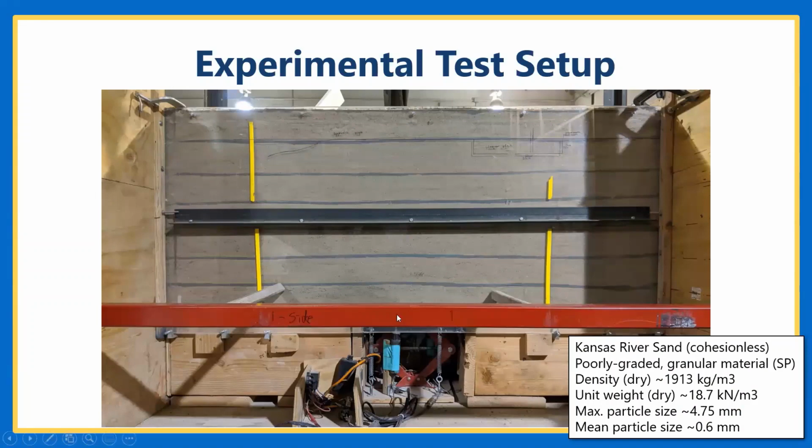So here's an actual picture of the sandbox. Down here at the bottom, you see that red electrical jack. This aqua colored thing is holding up one of the displacement transducers. We had 2 deployed, one on an opposite corner, and that helped me determine how much the trapdoor was moving. I controlled the downward movement of that trapdoor. You also see these black lines in the sand, which is black dyed sand to help us better observe any changes in the soil structure.